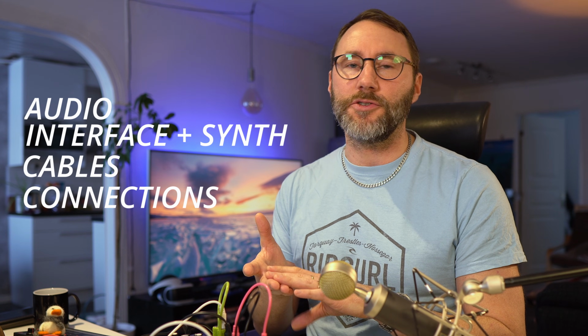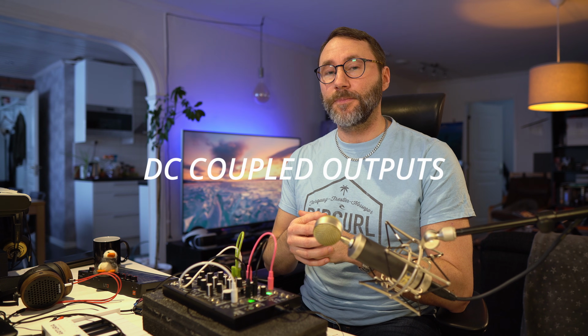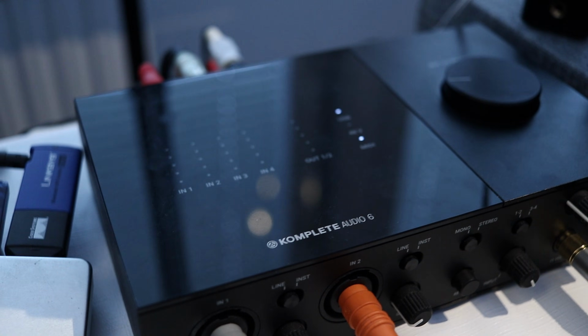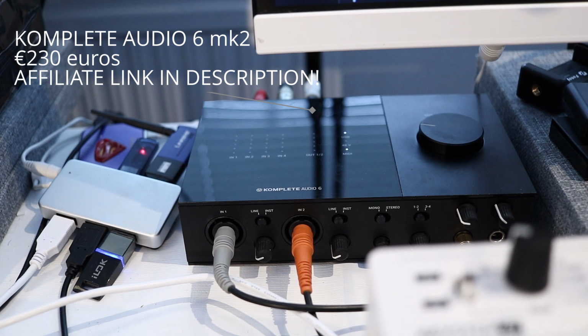Before we dive into the grid and Bitwig Studio, we need to talk about the gear, cables and connections used in this demo to make the signal connection work. To make this happen, we need an audio interface which has DC coupled outputs, so that we can get our control voltage signal out of Bitwig the Grid and the audio interface into our modular synth CV, trig or gate input.